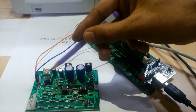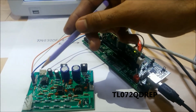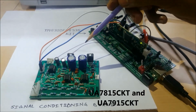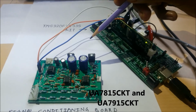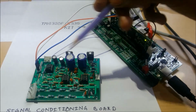The third op-amp is used for wave shaping, if required in future, for zero voltage sensing. This section of the circuit is the rectifier and voltage regulator consisting of the UA7815 circuit and the UA7915 circuit, which are ICs used for producing plus 15 and minus 15 volts.